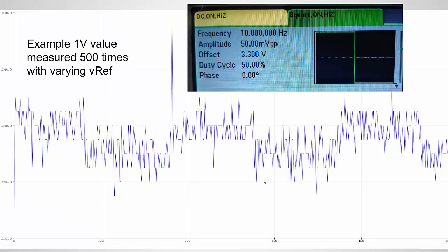And here's an example where I'm trying to represent, let's say, load regulation error in a power supply. So here's an Arduino Zero making 12-bit measurements, right? And I feed in an external voltage reference. I'm not going to go over the code for this, but I'll post it on my blog if someone's interested. The VREF external signal from a waveform generator is 3.3 volts DC, so this will be a fairly clean signal. But I added a square wave on top of that that's only 50 millivolts peak to peak and has a frequency of 10 hertz. I'm doing this to simulate load regulation error.